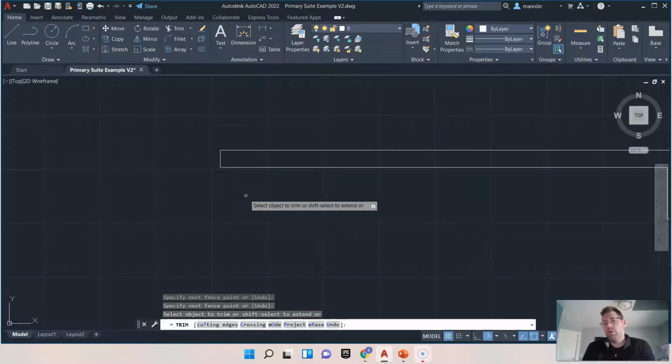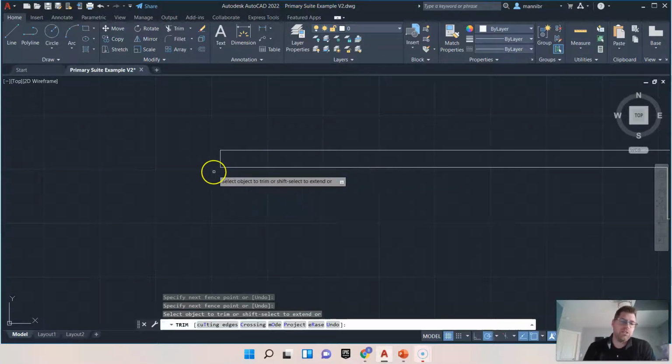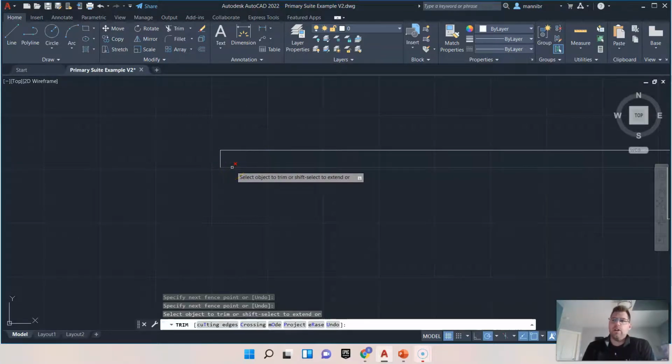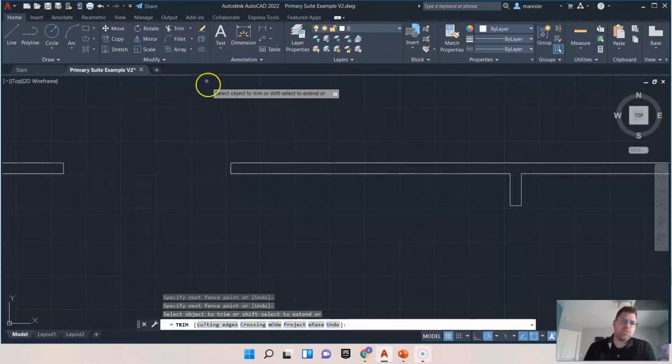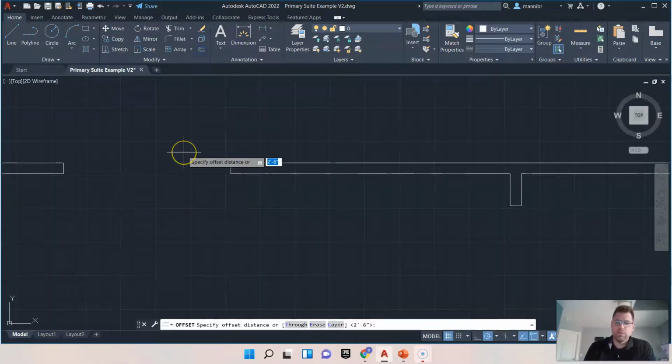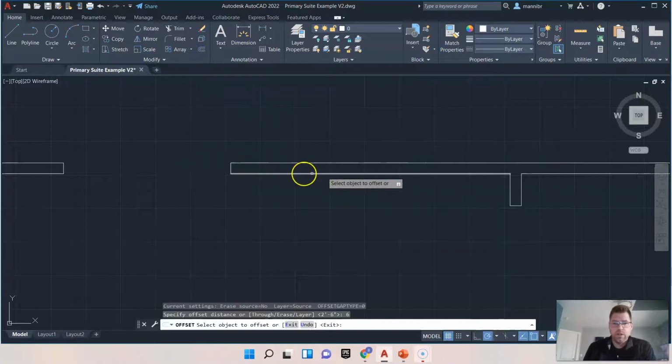I also have to think about window casing. How big is that going to be? Usually it's 2 inches. So I need like 4 inches from that standpoint, and I would have like a little bit in the middle to paint. So like 6 inches is the minimum. So let's just run with that. So I'm going to type in 6, enter.